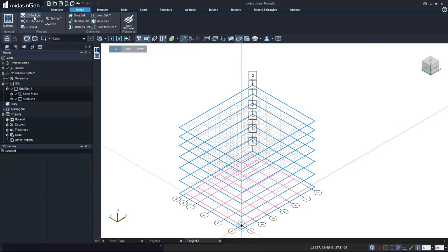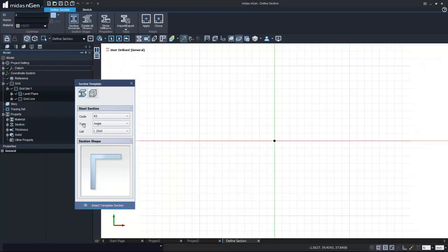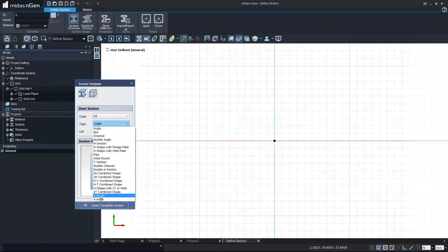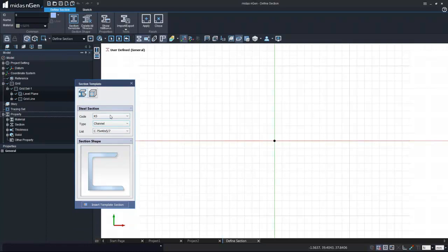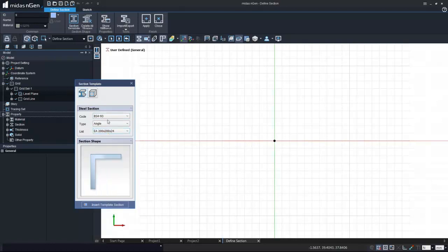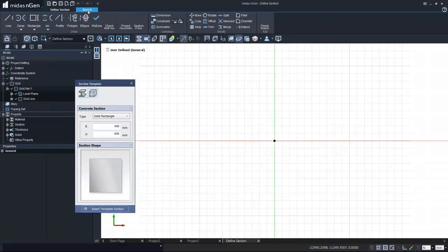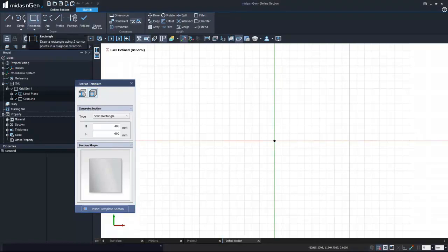Then further there is definition for 1D section. This is also very interesting. You can have some predefined shapes. Several predefined shapes are there as per the code. There is again a huge database for the shapes. So BS standard is there for the steel. When it comes to RC, you might have irregular shapes. So you can actually sketch your irregular shape over here.